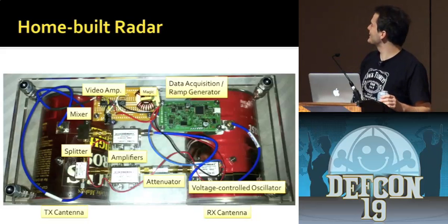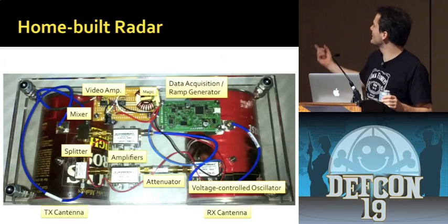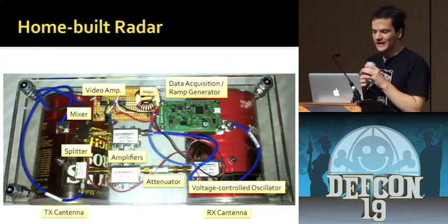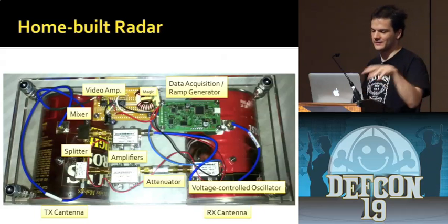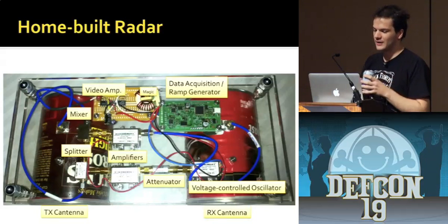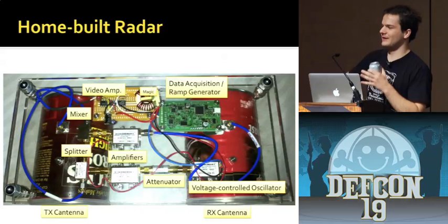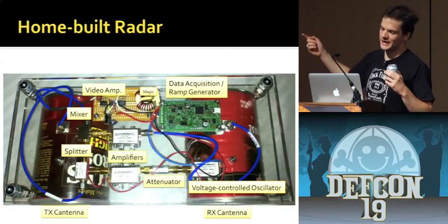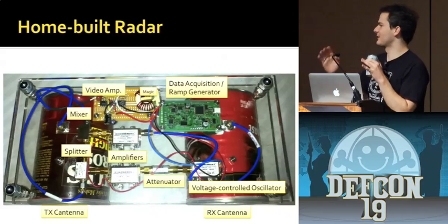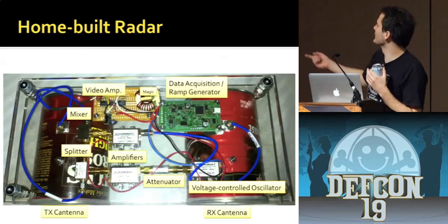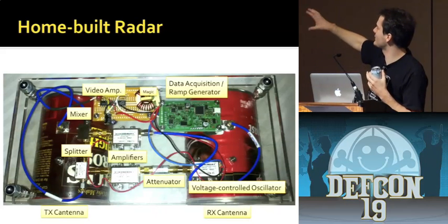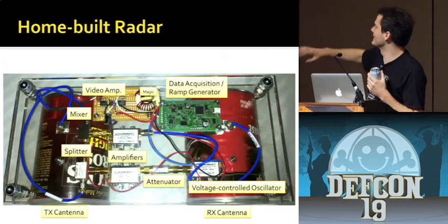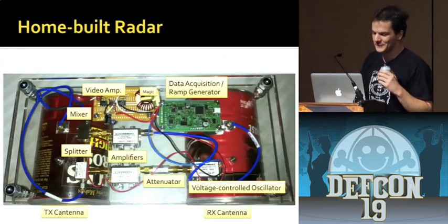Oh, so the reason that's there is because when I was trying to make this thing USB powered, I just wired it onto the power for this other stuff. Everything on here runs off of 5 volts. So I plugged the USB in, and then the computer doesn't like that. It just turns off the port. The problem was the inrush current was too high, and I needed something to slow that down. So I was like, okay, I'll put an inductor in there. And the only one I could find was this big choke transformer thing. So I just shoved that in there, and that worked. So that's all that's for.